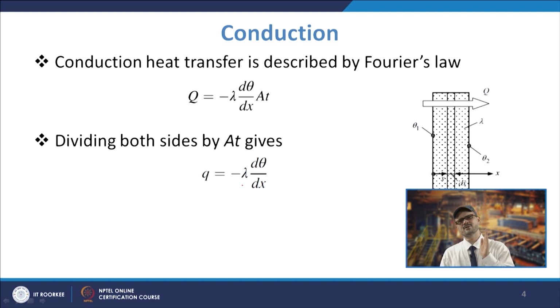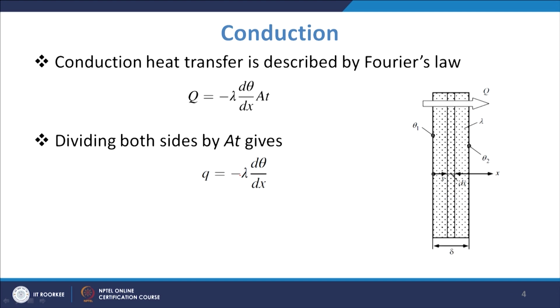You need to specify the material of the wall. So, if you have the refractory, you need to provide the refractory material with the appropriate value of the thermal conductivity. That will be varying for different materials. There may be ceramics of different types, and you can take the thermal conductivity values from the literature.